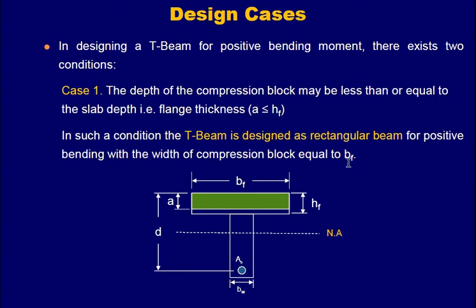The only change in this case will be that instead of B, you are now using BF, and you know how to calculate BF. You know the formulas for T beam, you know the formulas for L beam. And as I explained earlier, T and L are just their geometric representation. Okay, not T beam design. T beam design is different.